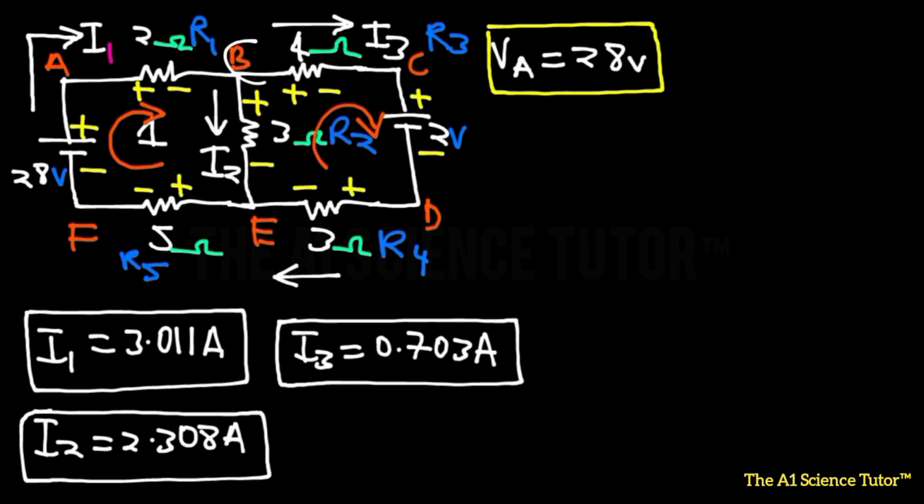Now what's going to be the voltage or the potential at point B? As the current moves from point A to point B, it's going to come across the resistor of 2 ohms, and that would reduce the voltage. That's the reason you say there is a voltage drop at that point. So what's the voltage wasted over that resistor? We could call that V1. Sometimes you could be asked to find the voltage wasted over such resistors.